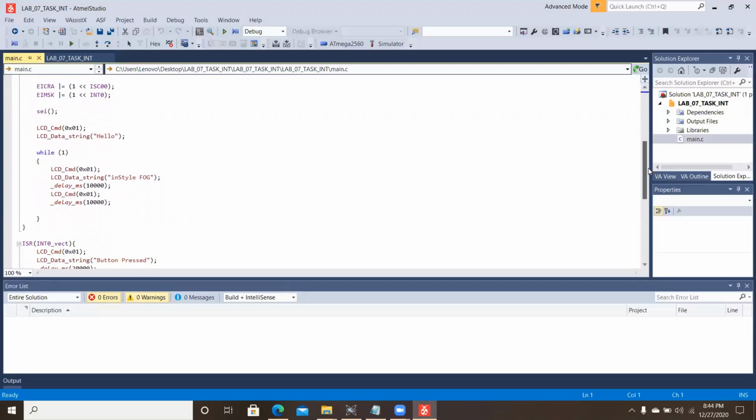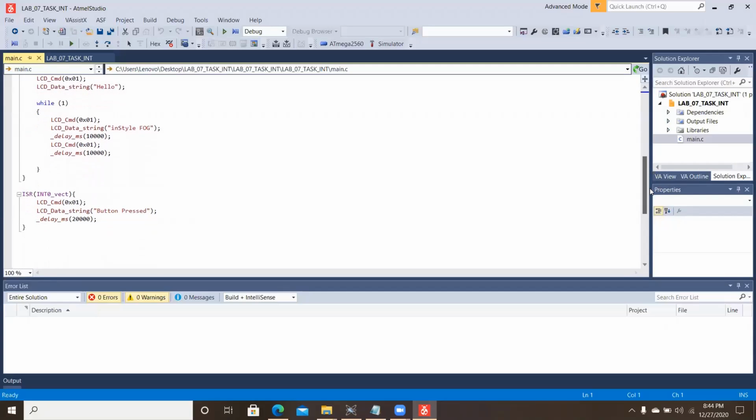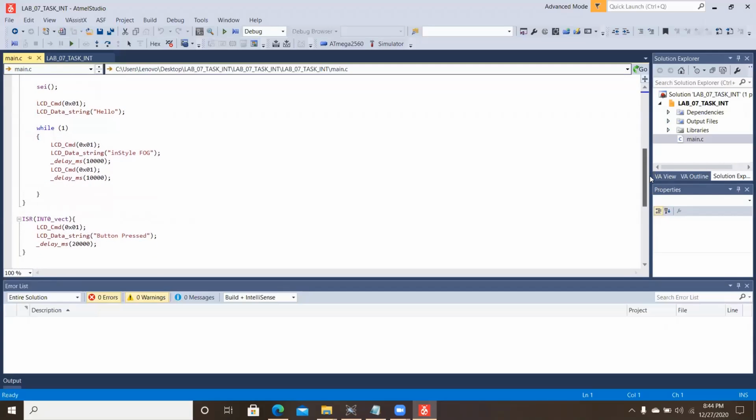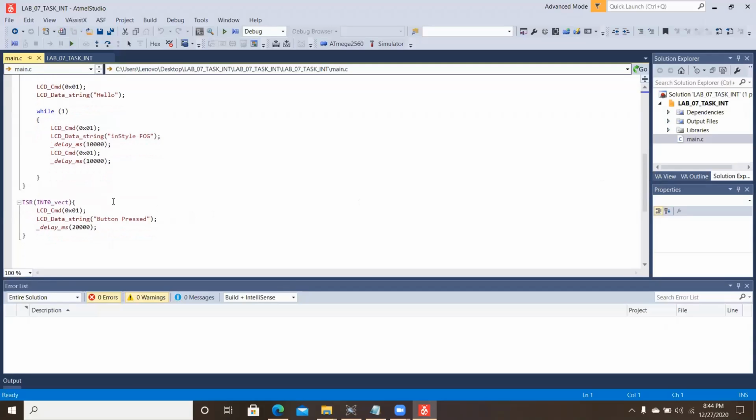And then in our main function, in this interrupt function, where the INT0 vector is called, our button pressed is shown, and when we press a single button, it will show interrupt 0 is called, and when another button is pressed, it will show interrupt 1 is called.